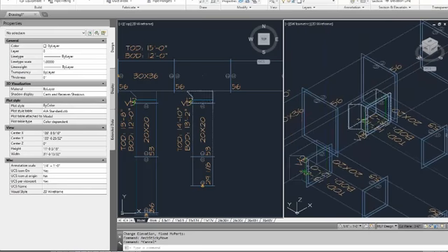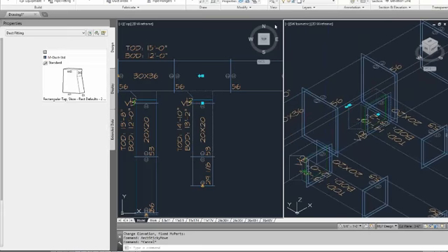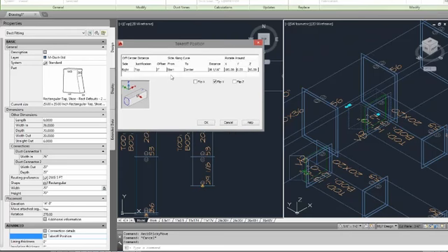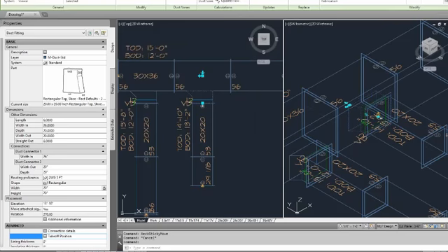So once you understand the tap anchors, and to make sure you get the correct anchor, using this takeoff position dialog, it's very simple to get your duct positioned where you need it to be. So if I need to move that 4 inches from the top, I just change that to 4 and hit OK. You can see that my tap moved down.